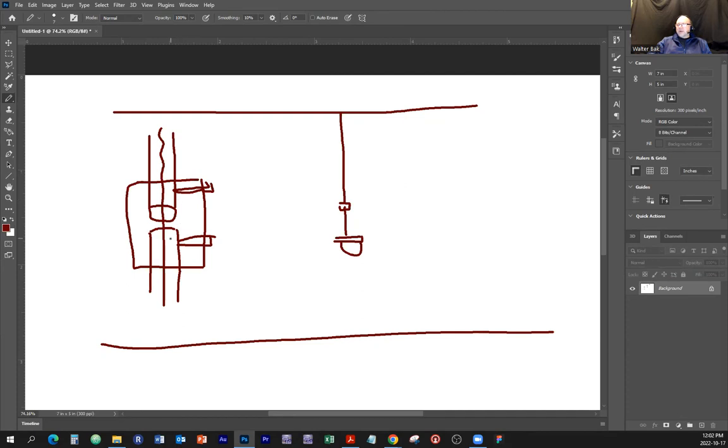Because they are not meant to hold weight, usually what I would do is drill a tiny hole. You have to be careful, you could do it before you run the wires. Drill a hole maybe here, drill a hole maybe here, and run a steel cable and join them here, to provide safety. So if something lets go, it's not going to fall down on somebody's head.